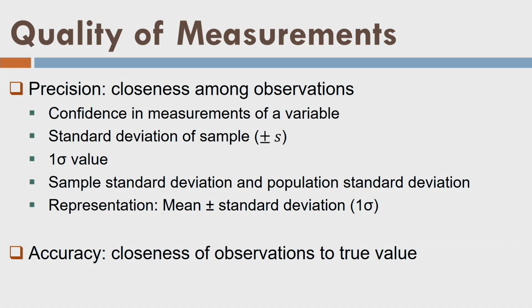So now let us say we have taken repeated or replicated measurements and I have multiple measurements with me. Let us say the length of this room I have taken many times, 100 times, 200 times, 30 times, 1000 times, but I have multiple measurements. If I take the average of those measurements, I will have higher confidence, because the errors in those individual observations are now minimized by taking the averages, because the errors cancel each other. There are some positive errors, some negative errors, some large errors, some small errors, but they are again positive and negative.